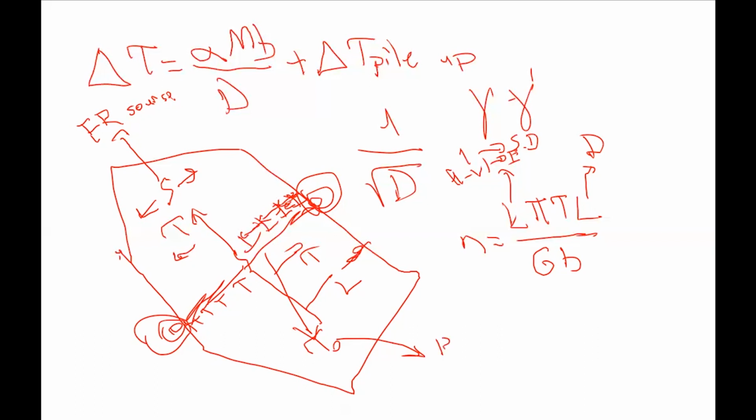So this is, let me call it, Peierls stress. For FCC material, the lattice resistance is very low, maybe 5 megapascal, even 1 megapascal, depending on the temperature, of course. But for screw dislocation, it is very high. The lattice resistance is high. And the lattice friction stress opposes the applied shear stress.